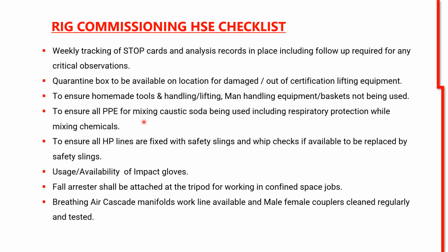To ensure all PPE for mixing caustic soda being used, including respiratory protection while mixing chemicals. As we know what chemical we are using and what PPE we have to use for the chemical depends on the MSDS of that chemical. And nowadays the MSDS is SDS. Okay, MSDS stands for material safety data sheet, and SDS stands for safety data sheet.